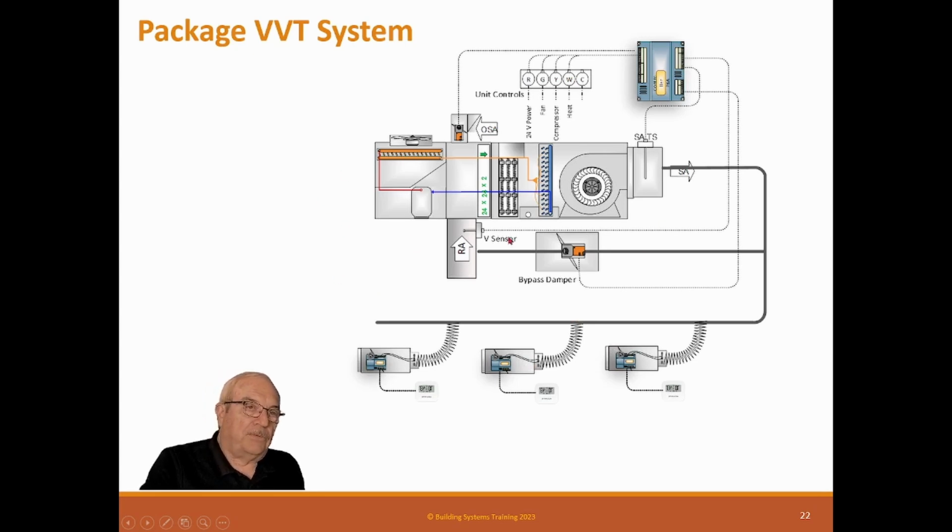These were really popular 20, 25 years ago. And one of the problems that made them not work too well is each vendor came out with their own system, and they had some really squirrely designs. The problem is that back then the digital controls were not near as far along as they are now. And so they had a hard time. So they put zone sensors out to override boxes and to control it. And it turned out that control basically bit them because it didn't work very well. And a lot of systems didn't work well, and so their popularity plummeted because their systems just couldn't operate.